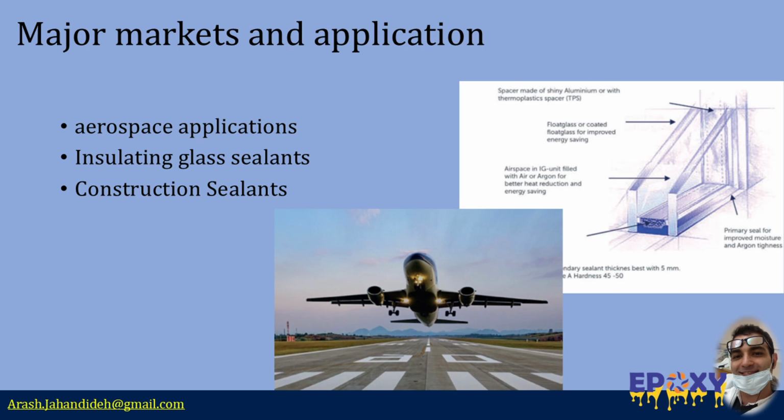In aerospace applications, the importance of liquid polysulfides becomes even more evident. Sealants based on these materials are extensively used in the sealing of integral fuel tanks, aircraft fuselage joints, and window systems. They are also formulated into potting compounds for electrical components within aircraft systems.